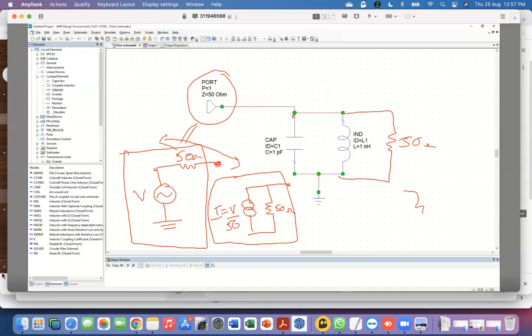And this 50 ohm, why it is 50 ohm is again a convention, which I will explain in one of the upcoming classes. This is the convention which is used, that everything has this particular characteristic impedance and a source impedance. So right now we have only talked about source impedances. We will talk about the characteristic impedance in just a little bit. That'll be the last thing I'll cover today. And these all have to be the same because we are really talking about waves now, and these represent the condition where waves can propagate without having any reflections in various scenarios.